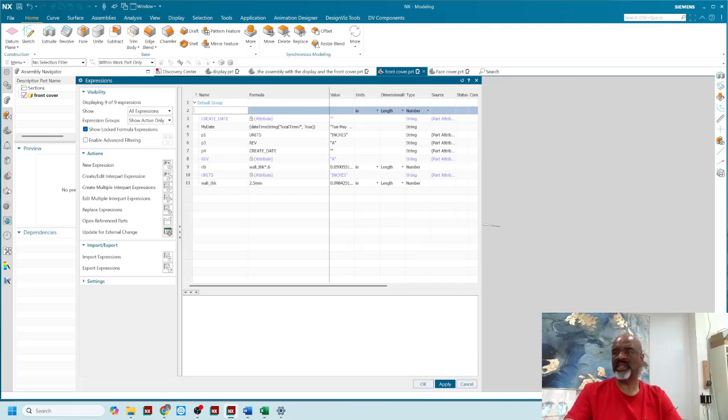and that's really good. I'm also going to use some self-tapping screws, some M3 self-tapping screws. And in general, if I'm going to use ABS, the hole that I'm going to put in my screw boss is going to be 85% of the diameter of the screw.